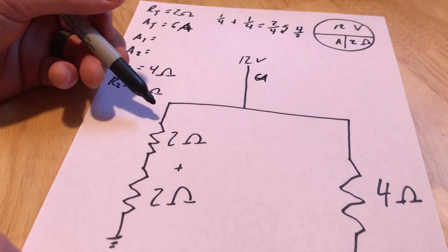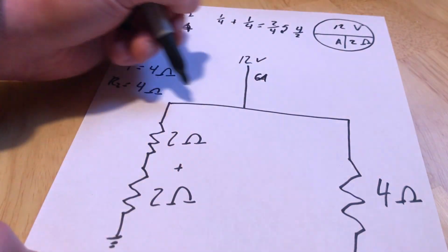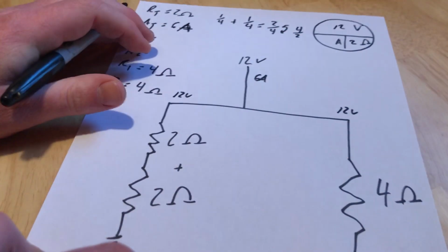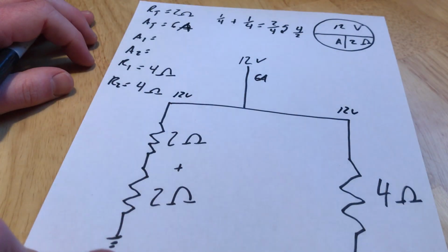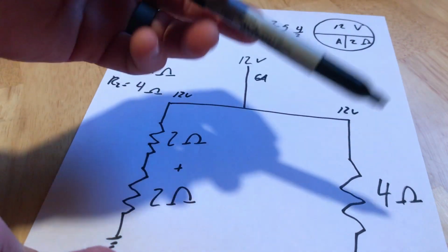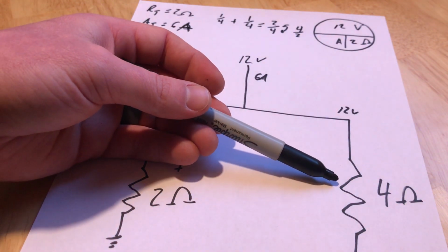And now I want to figure out how much is going to go each way. Again, no resistance between here and there, so I'm just going to turn these both into little series circuits. And this is what's happening all over the car. We've got a fuse panel, and each fuse powers up a few different things. And really what we're doing is like, hey, my power window motor has 12 volts applied to it.